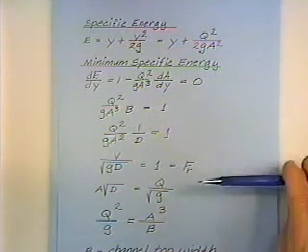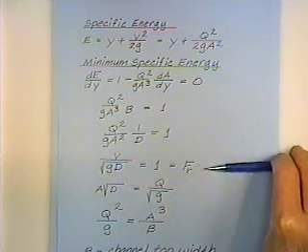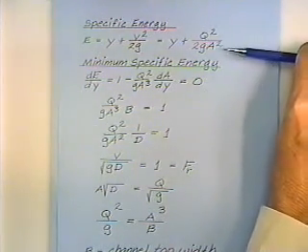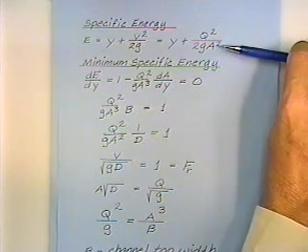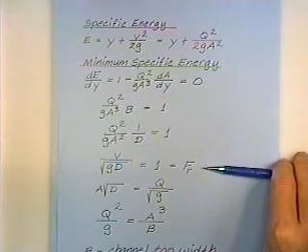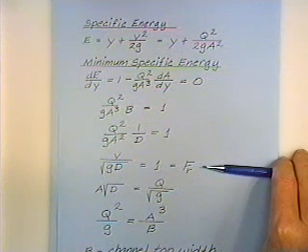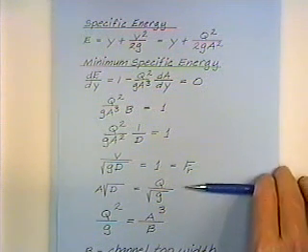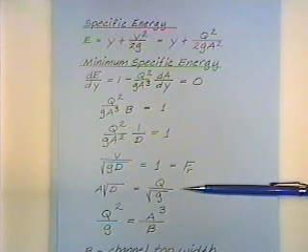What we've just proved to you is that minimizing the specific energy results in the Froude number being equal to 1. Then you can rearrange that a bit and get this equation. Some of the textbooks and references use the equation in that form.